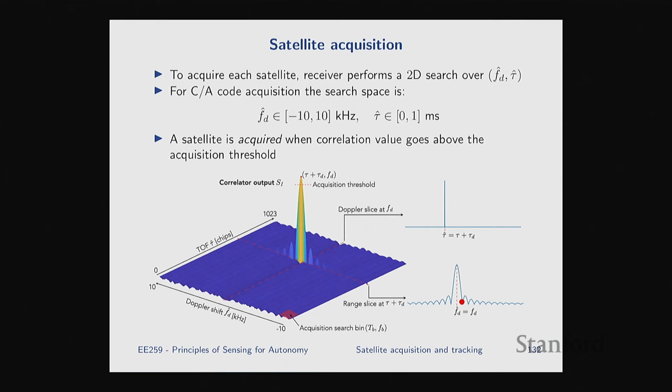It's still a pretty sharp drop. Remember that end to end, this is just 20 kilohertz. You can be off by a few hundred hertz and still have a decent output out of your correlator. But if you're off by more than, I don't know, 250 hertz or so, you almost entirely kill the correlation output. And that's actually a good thing.